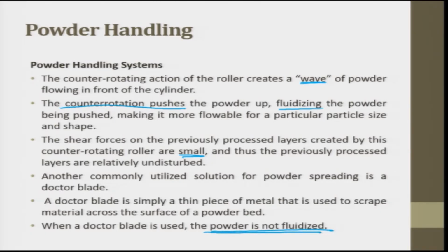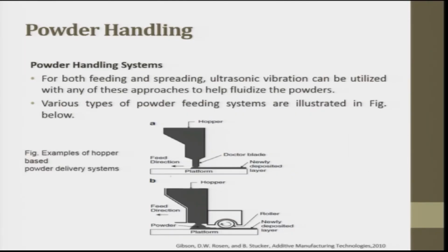In a fluidized bed, you use pressure also to move it. So, examples of hopper based powder delivery systems, you can use. For both feeding and spreading, ultrasonic vibration can be utilized with any of these approaches to help fluidize the bed.